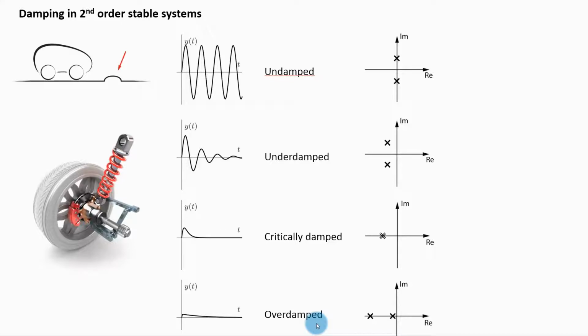So what is the minimal amount of damping we need to provide to suppress oscillations? Well, that is the critical damping, when the system has the critically damped response. With this damping, the damper allows your wheel to move the most without creating oscillations. So when you design a system, be that a wheel suspension or inverse pendulum or an autopilot in a plane, you probably want to achieve a response close to this one.